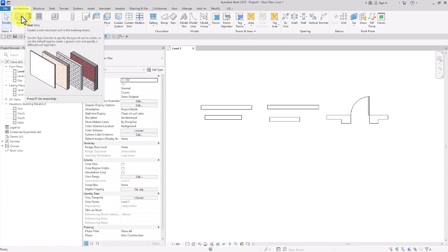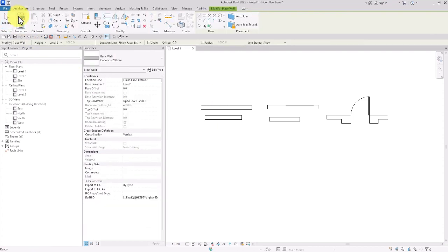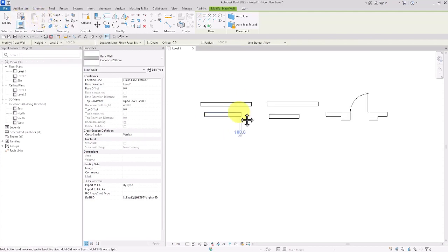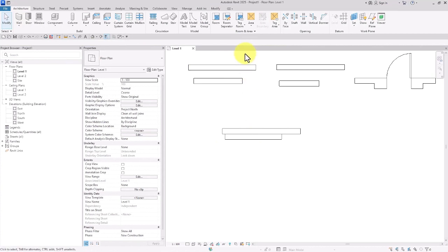Okay. The next point is, if you have created some walls in previous versions of Revit software, for example, 2024 version or 2023 and so on, some walls such as these, for example, and we know that these walls are obviously not joined because we didn't have these items. And when we open these walls in Revit 2025, it doesn't join them up automatically. And you have to go through the joining process completely manually. In other words, you get what you had in previous versions.